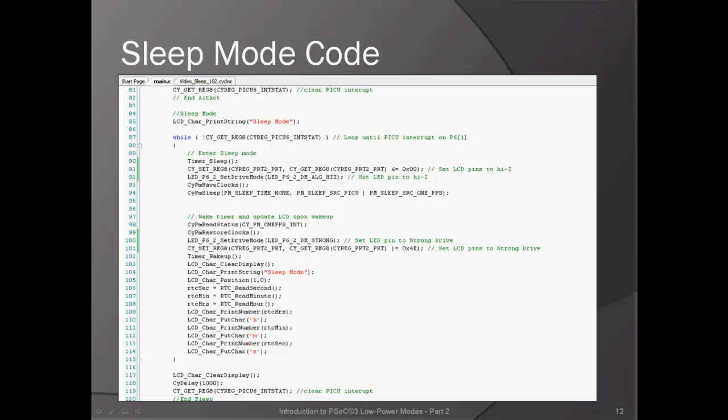You will notice that entering sleep mode requires some additional steps that alternate active does not. This is because most resources in the PSOC are disabled during sleep, so you need to properly prepare for it. Most Creator components have a sleep API which saves the current state and stops the component. If returning to the exact state that the component was in before sleep is not important, or if the component is not needed after sleep, then stopping the component will result in the same power savings.